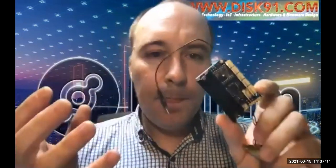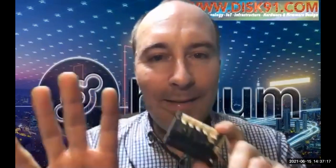The LoRaWAN stack is a bit big, but it fits here, and you still have something like 2 kilobytes and 100 or 200 bytes of RAM. So it's really limited, but if you want to measure temperature, presence, air quality or things like this, it's okay. You can do it with such a thing.